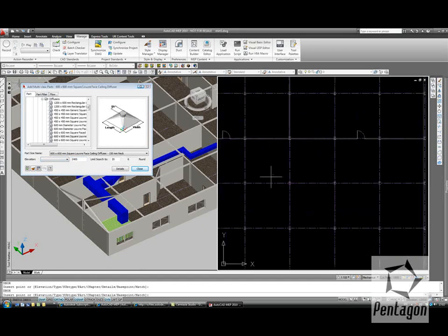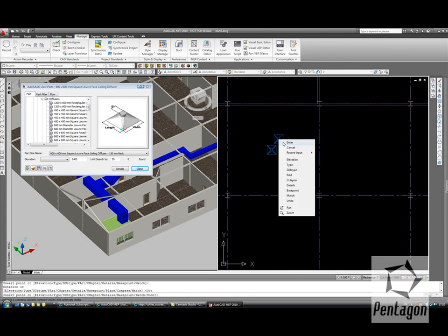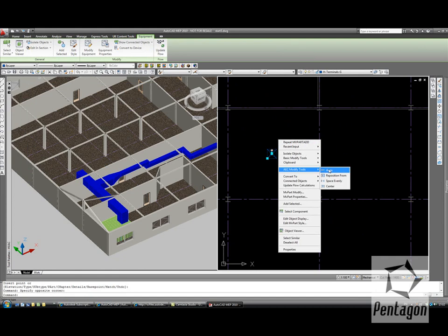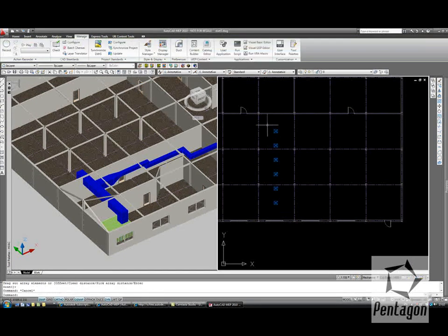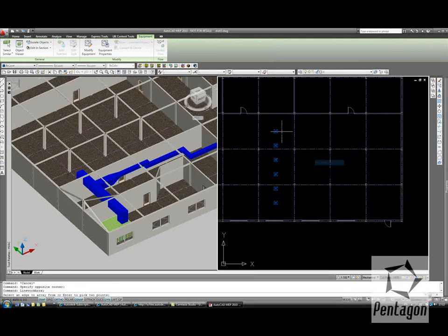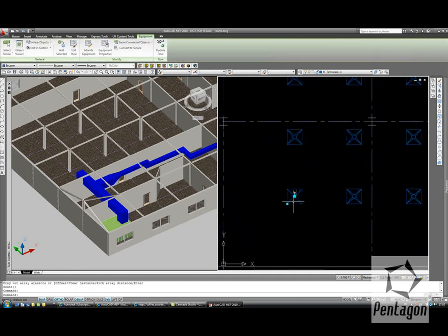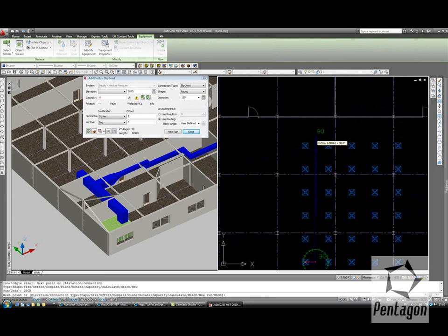By simply using the control key, I can swap out to the center of the duct or diffuser and get the position. I can use my AutoCAD tools to simply interact, or I can use my AEC Modify tools to actually create various duct layouts in here, or diffuser layouts. Again, we can simply interact on the screen or copy the data out. Let's copy out a few positions. So this gives me a good bit of flexibility here. So I can add on the plus on my duct and start working and tying in back as part of my design.